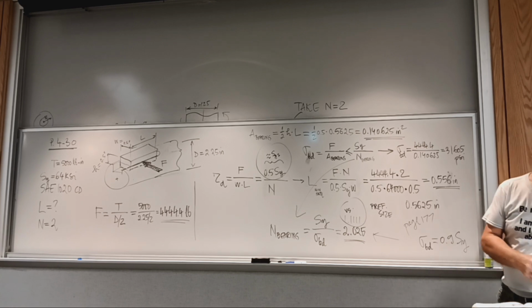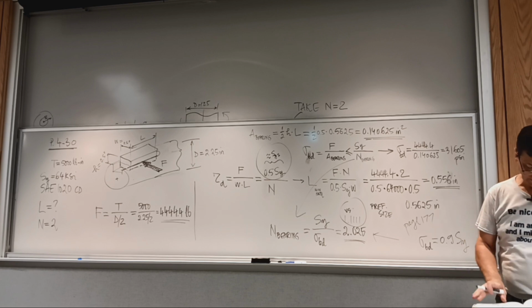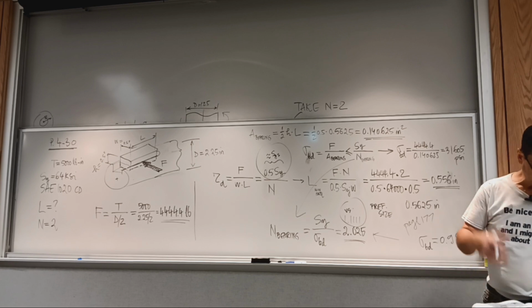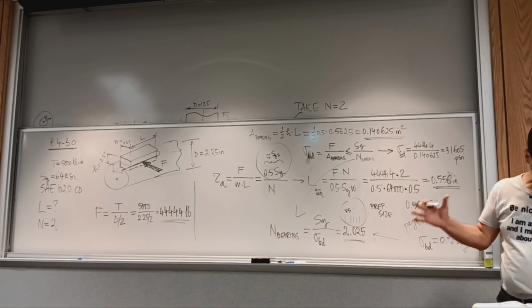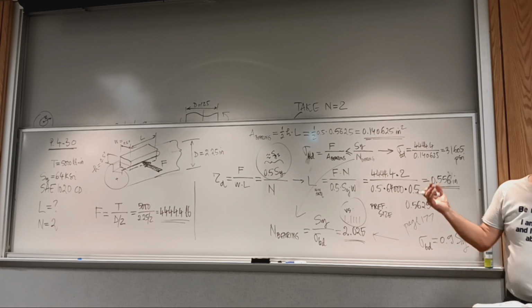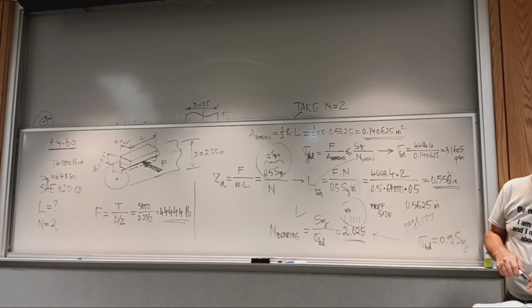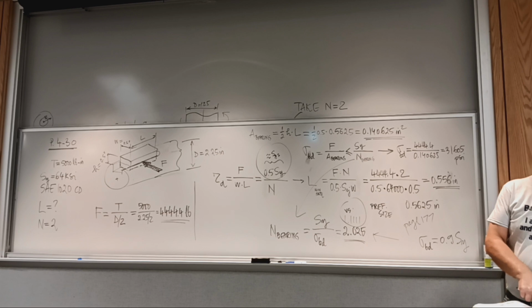All right, so we did yet another problem, and as I said, the theory is once you have the force and the area, it's pretty straightforward. And with other problems too, once you know the torque and you know the solid round or tubular shaft, and maybe the stress concentration factor there going on. Let's look at problem 416.